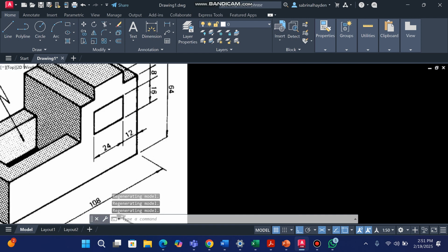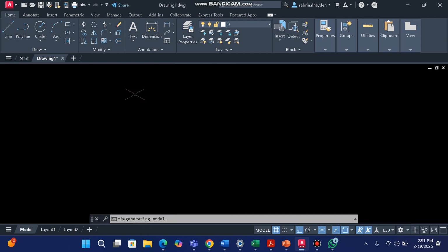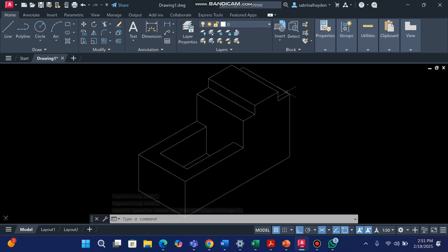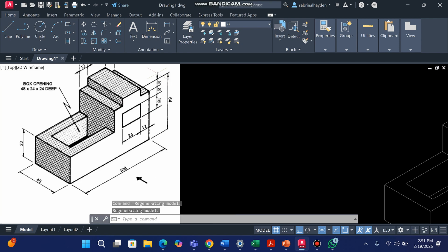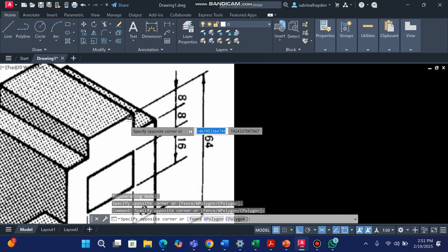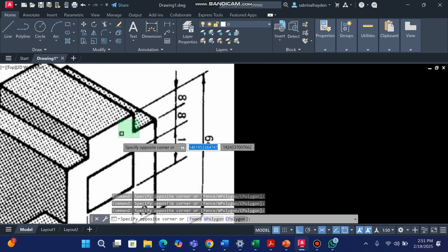So what we're going to do, again, the measurement is 16 because 8 and 8 is 16. So we would offset this line right here downwards going 16. Let me ensure that you understand how I got the 16. This tiny line right here, the one that I'm trying to highlight in green, is 8 millimeters. And the space right here going down is also 8. So 8 plus 8 is 16, which means the space that this line is from the face, the plan view up here, is 16 millimeters.